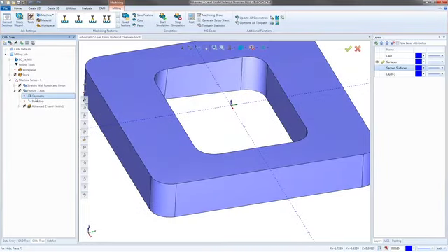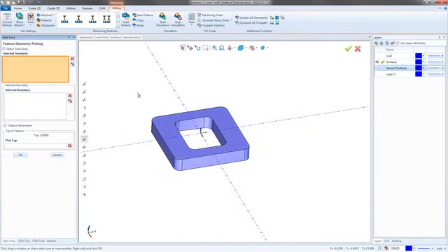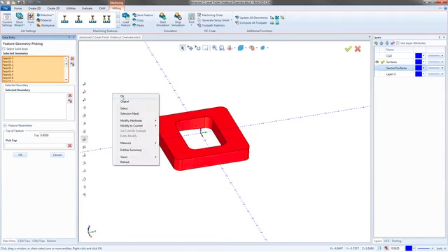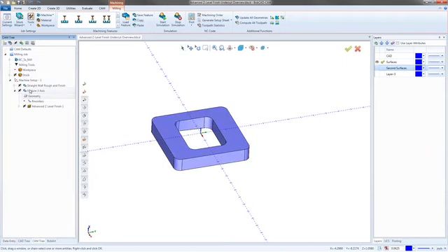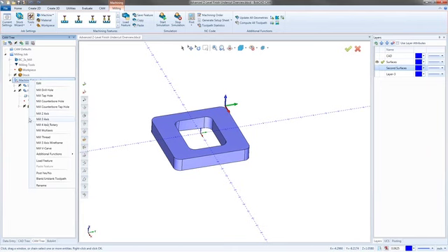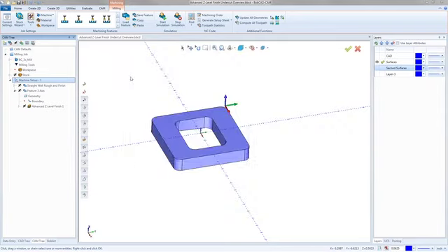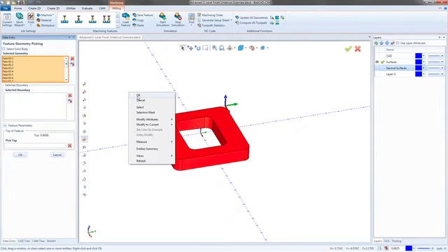So if I remove my old geometry and say reselect, again, I pick the whole part, I hit OK. Now with this toolpath, so let me go in, I'm going to recreate it as well. The problem that I run into is the depth of the part. The part's 1 inch thick. I need the tool, though, to go past the bottom of the part a little bit to clean up the walls perfectly. So when I go in here, I go into my mill 3 axis, pick my geometry, I pick the whole part, and I hit OK.